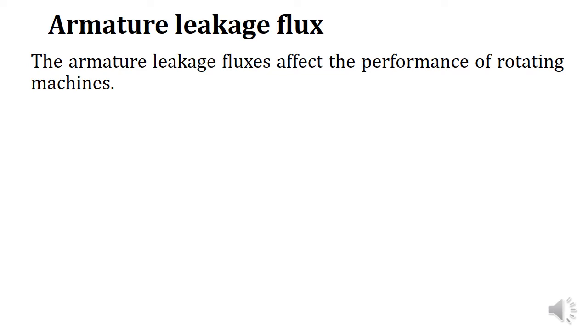For example, in the case of AC machines, the leakage flux causes leakage reactance voltage, which has an important role in the performance of AC machines. Similarly, in the case of DC machines, since there is leakage flux, we have to provide additional field excitation to compensate the loss of flux. And in addition to that, due to the presence of leakage flux, there will be reactance voltage produced, which affects the proper